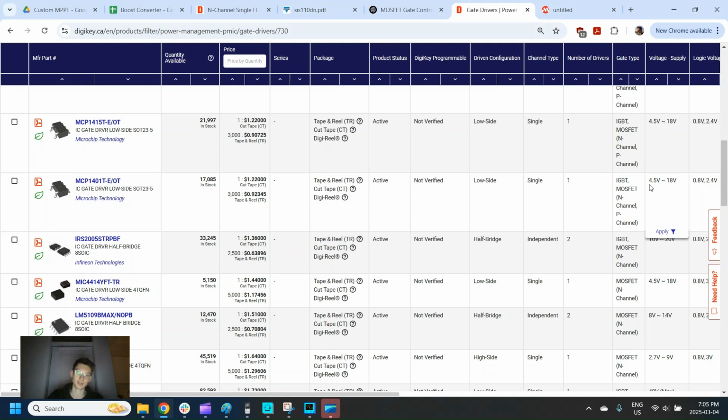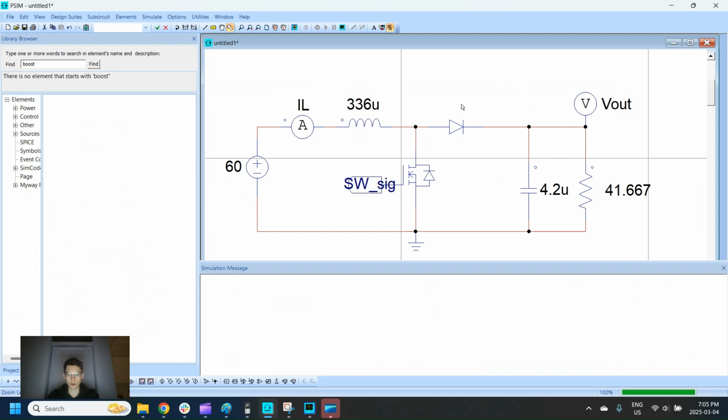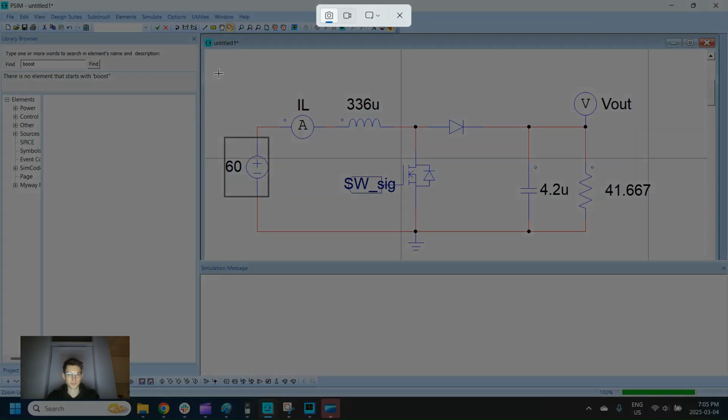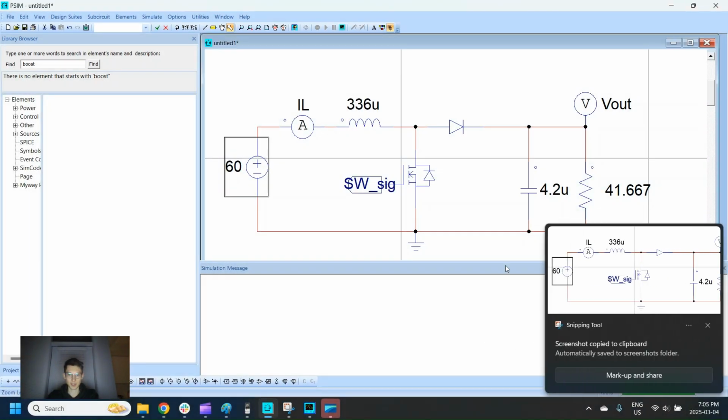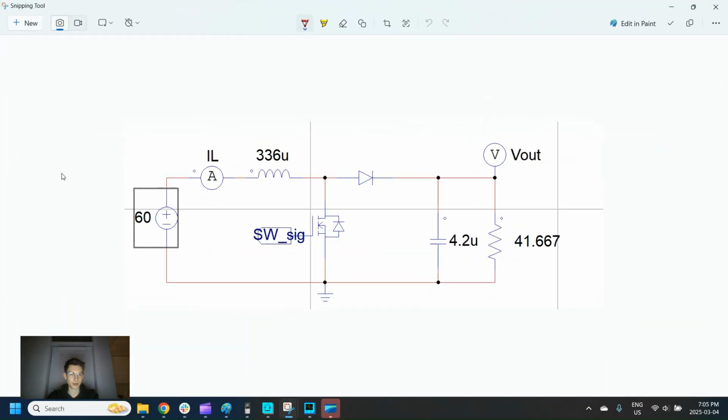So I'd also recommend adding a smaller buck converter. So this is your overall boost converter, but in order to operate this switch, we have 60 volts, and you can take the voltage here and just step this down using a buck, just like an efficient one you buy on DigiKey, to power our thing that's going to power the gate.